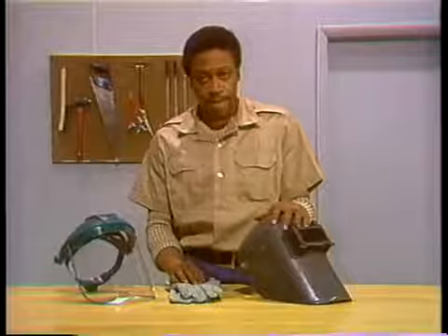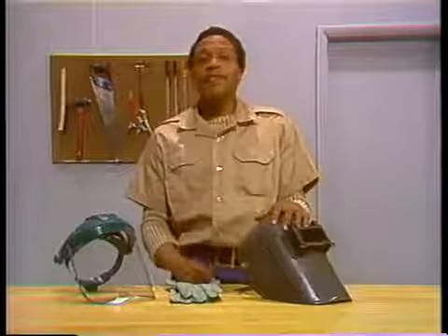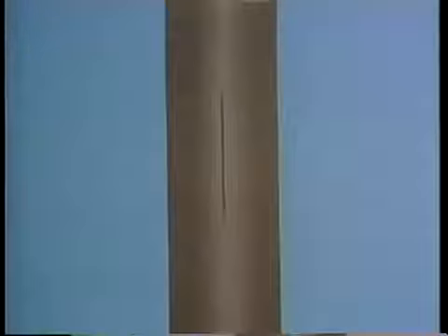To sum up, there are 4 steps in this weld repair procedure: heating and closing the rupture, grinding the edges and the surrounding tube surface, welding the edges together, and cladding the repaired area.